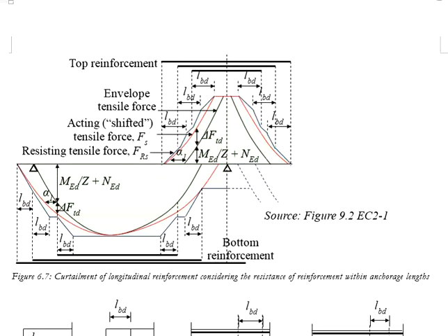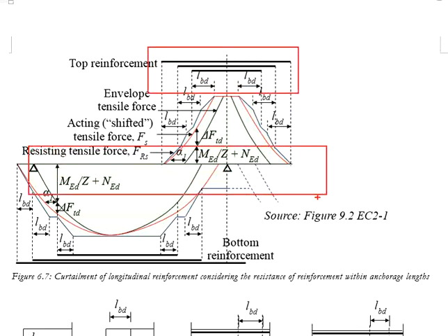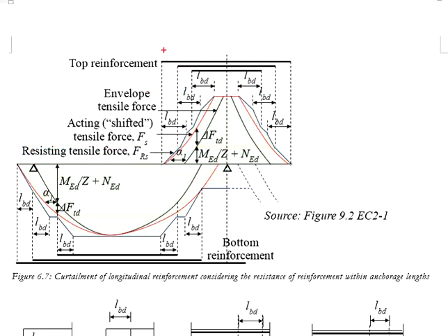For example, when you work out the top reinforcement bar in the continuous beam, theoretically you may stop all the reinforcement bar here, since this region has no hogging moment and the top part of the beam here is not subjected to tension. Instead, it is subjected to compression, and just nicely the concrete can withstand the compression.